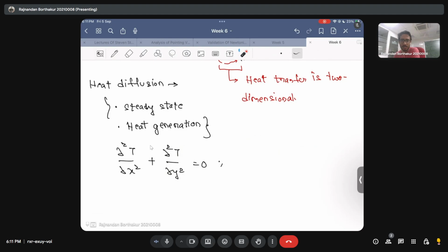But now, as you can see, it's a PDE that we are dealing with. So first of all, the change that you can see is that the ordinary differential d/dx now changes into del/del x, which means that we are writing a partial derivative, which is second order. And the prime reason is that your T is now a function of two independent variables. So differentiation in T needs to be done with respect to all the independent spatial variables, and that's the reason why we have a del x instead of an ordinary differential operator d/dx. Okay, that's the first change that you see.